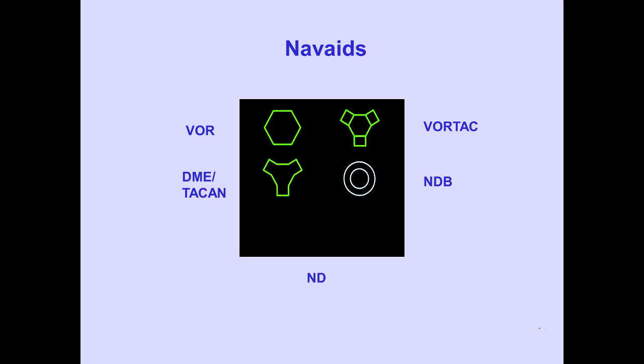The VOR, VOR-DME, TACAN, and VOR-TAC station symbols are as shown. Tuned Navaids are displayed green, others are displayed blue. NDBs are displayed in blue.